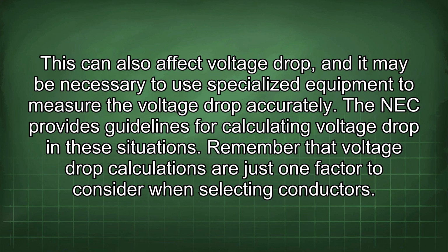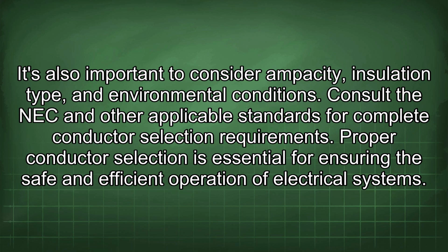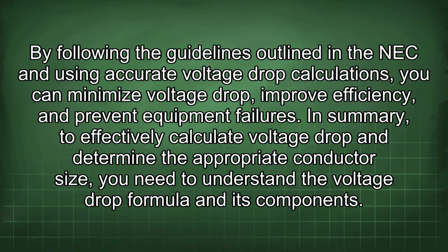Remember that voltage drop calculations are just one factor to consider when selecting conductors. It's also important to consider ampacity, insulation type, and environmental conditions. Consult the NEC and other applicable standards for complete conductor selection requirements. Proper conductor selection is essential for ensuring the safe and efficient operation of electrical systems. By following the guidelines outlined in the NEC and using accurate voltage drop calculations, you can minimize voltage drop, improve efficiency, and prevent equipment failures.